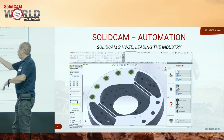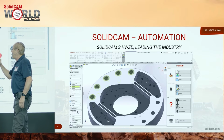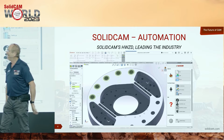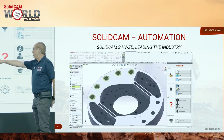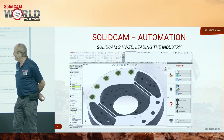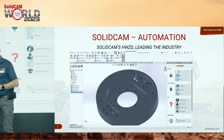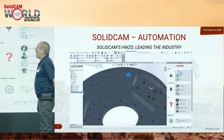So as we're going through the steps again, it's a 17 millimeter hole and a 32 millimeter counterbore. I feel like we needed a reiteration on that, right? Right, exactly. Repetition builds memory. And don't forget the tolerances that I talked about before. This is a test, so you're going to be asked about this question. That's why we're going over it, just to make sure you know it. And of course, the actual dimensions.